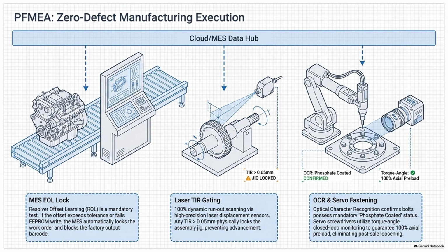It's a great question, and the answer comes down to the fundamental laws of induction, specifically Faraday's law. Okay, take me back to physics class. Search coils measure back EMF, but back EMF is only generated by a change in the magnetic environment, meaning the motor has to be physically spinning. When you are stopped dead at a red light on a steep hill and you need maximum instantaneous torque at exactly 0 RPM just to get moving without rolling backwards, the search coils produce exactly 0 volts. They are completely, utterly blind at 0 speed. Because nothing is moving, no magnetic lines are being crossed, so no voltage is induced in the search coils.